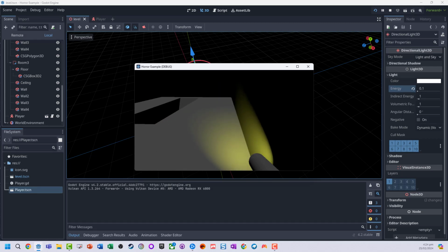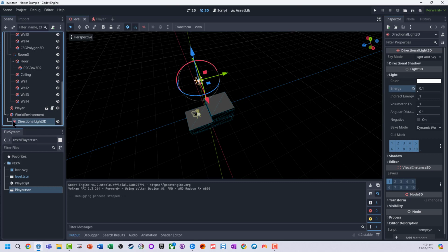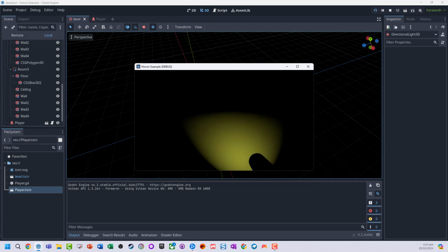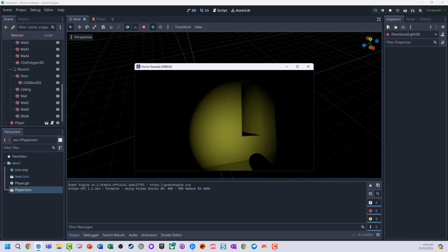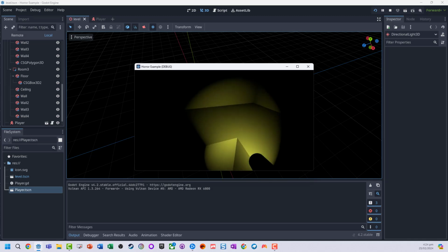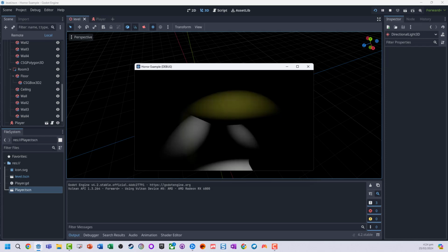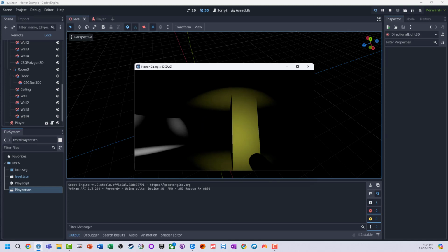Note, it does seem to go through a few other shapes, so you probably don't want to worry about using a directional light. Use some spotlights, particularly if you're working in a horror game. You've got close environments, so think about the angles that you want to use. Light distances, use light to play around with what you want to see, because you can get some quite good little horror effects coming through here. So that's how we can add our core lights.